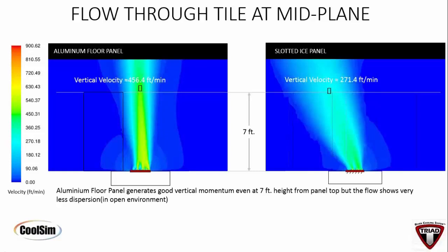Yeah, the rocking chair anterior fin does create a directional flow, but because of our intentional design of our pattern to change laminar flow from underneath to turbulent flow above, it actually fans out. So it does create the direction I think they're talking about, but it also creates a turbulent flow which transfers the heat across the face of three servers.